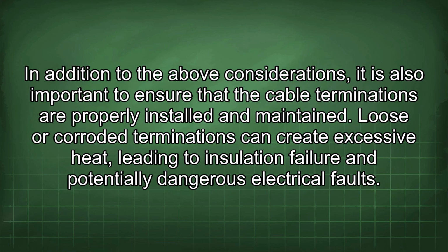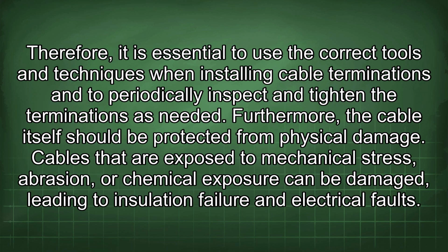In addition to the above considerations, it is also important to ensure that the cable terminations are properly installed and maintained. Loose or corroded terminations can create excessive heat, leading to insulation failure and potentially dangerous electrical faults. Therefore, it is essential to use the correct tools and techniques when installing cable terminations and to periodically inspect and tighten the terminations as needed.